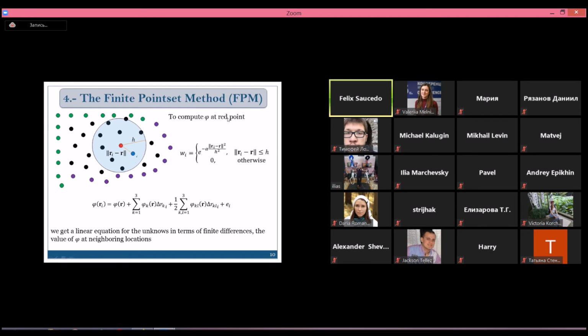traditional methods? Okay, yes. As this is a Lagrangian method, a Lagrangian formulation, this method will always be better than mesh-based methods when you have high deformations in the computational domain, or for example, when you have fragmentation of the computational domain. This method will always be a good candidate, or sometimes the best candidate to model this kind of problem, because